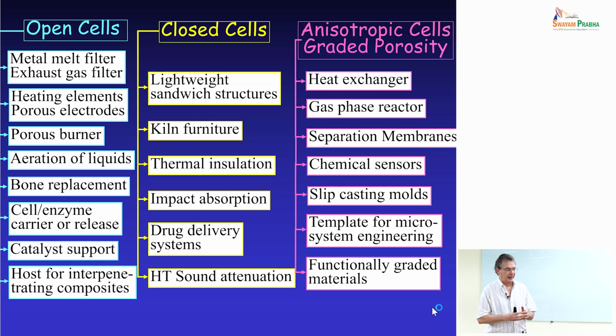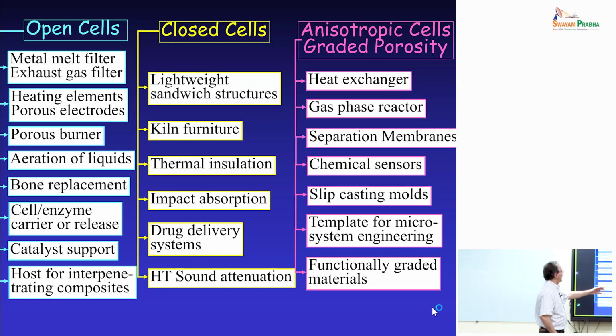The ceramic typically has a high elastic modulus, certainly high hardness. One of the things that we found out, so we did that with the idea of increasing the hardness of the metal. But what we found is that when you do a wear test, the ceramic foam fractures, and if you quantify the wear by the weight loss, then you have chunks of material that are released, and the wear resistance appears to be lower. But there are other people that have demonstrated that you can make components with very interesting properties if you combine metals with cellular ceramics. If you have closed cells, this is a wide range of possibilities for applications.